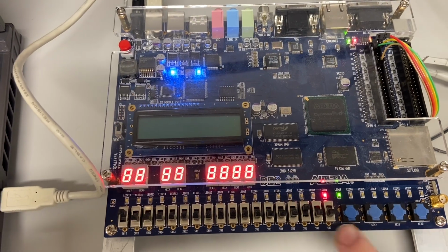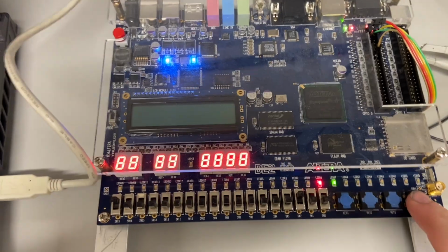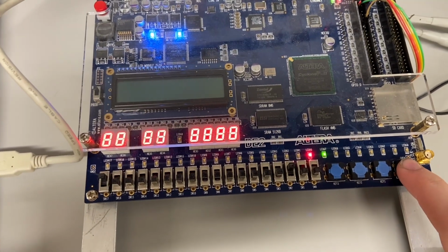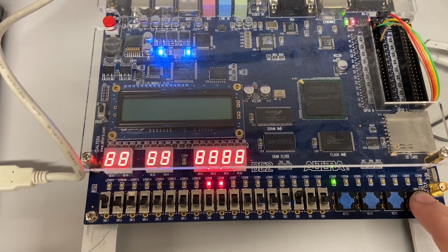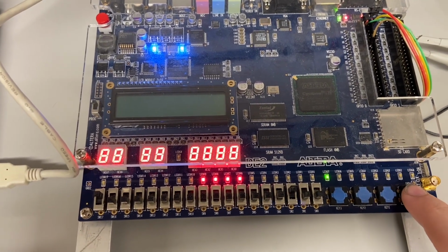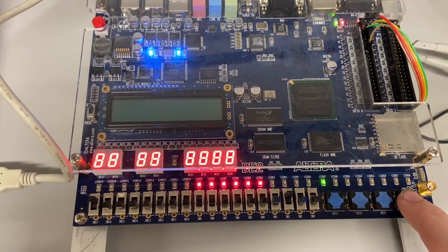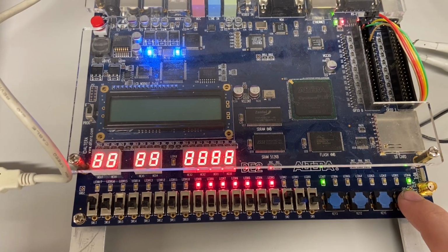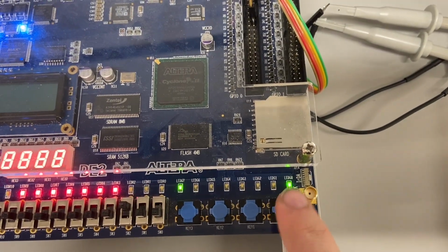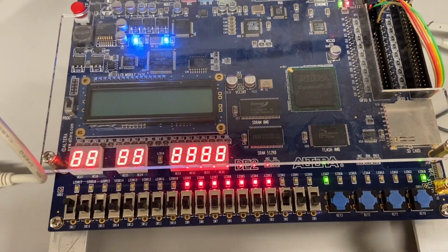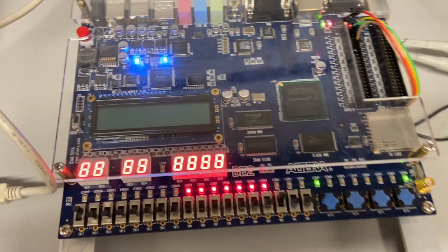we continue, you can see that it's rotating the bits. We can't see the rotate out for this, so we're only seeing the bits get rotated out. So then now it incremented the top bit, and there is a clock cycle between the rotate out and the data out. And then you can see right here, this green dot right here went high. This is our finish flag. So now we know that 20 cycles have gone through, and this is now -4, so it's working correctly.